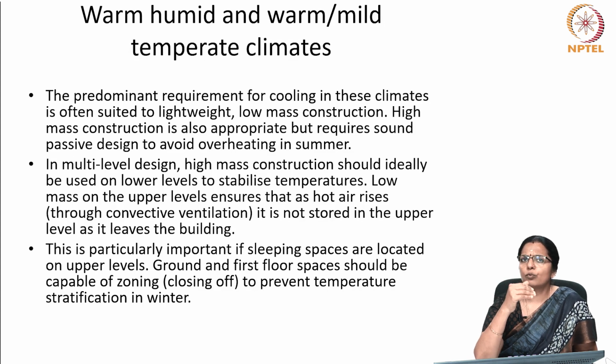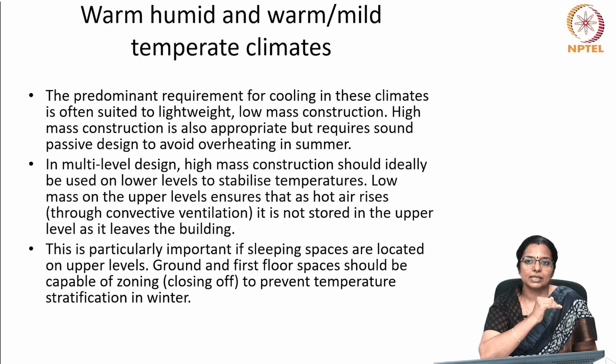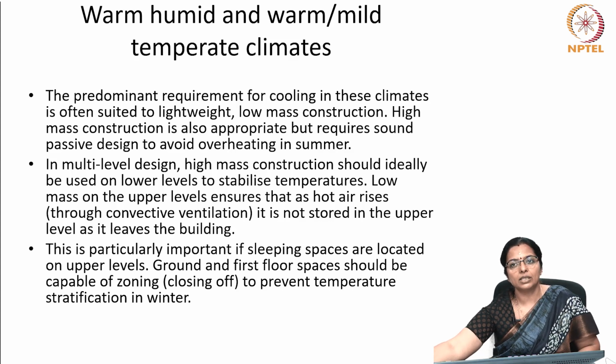What should you do in warm, humid or warm and mild temperate climates? The predominant requirement for cooling in these climates is often suited to lightweight, low mass construction. High mass construction is also appropriate, but requires very sound passive design to avoid overheating in summer. In multi-level design, high mass construction should ideally be used on lower levels to stabilize temperatures.